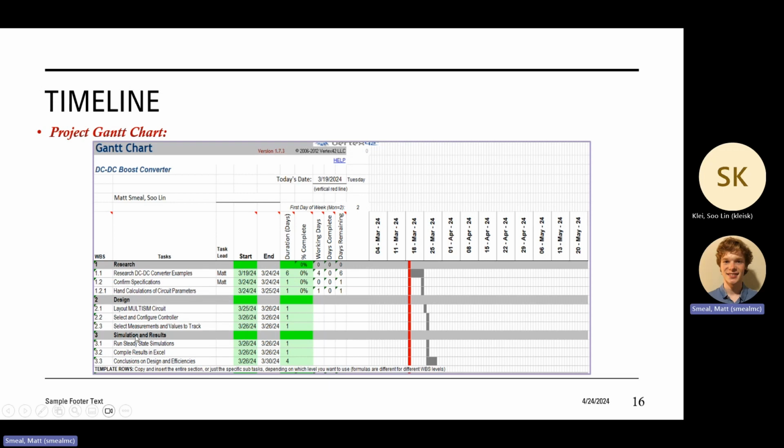And then we did the Multisim circuit. That didn't take too long. There was a lot of work to fix that spiking at the beginning. So we just chose the simplest one, which is a parallel capacitor. A snubber circuit would definitely be best.